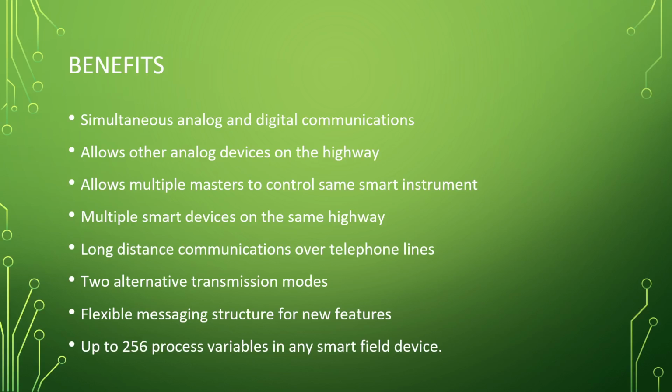Because it's like, hey, you two, go over there, replace that sensor. You two, replace that input card. Third person's on the PLC saying, okay, here's going to be the new input card. Here's where things are going to be wired. Update the tags, and boom, you're done. Compared to, okay, we got to run a new wire for this, and depending on where you're running that wire, you may have to do a machine down for that wire run. Oh, that's not going to make your boss happy. So there's a lot going on, a lot of benefits here for this HART technology. But there's obviously some downsides to it as well.